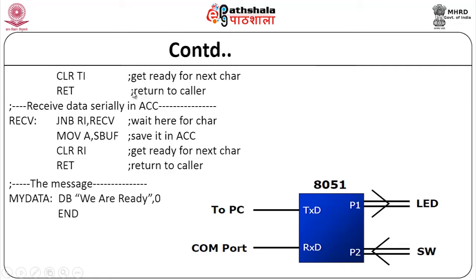That means whatever data I wanted to send, I will send it from the SBUF. A to SBUF I have placed. Now I am monitoring TI, it has been sent.